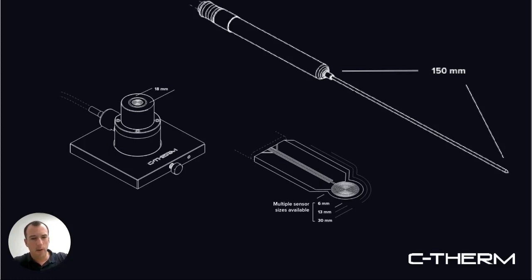And one of the things they find really helpful to do is to actually map some of the different regions of a manufactured piece to better understand how well the additive is being distributed, because so often when we're talking about nanocomposites or filled polymers, the challenges of achieving a higher effective thermal conductivity are often related to the challenges of achieving a good distribution of that additive material, whether that be glass fiber, boron nitride, carbon nanotubes, whatever you're using to help improve the heat dissipation.